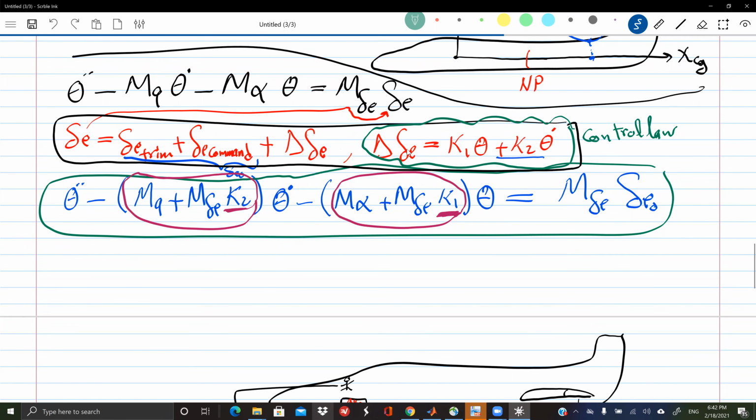If someone magically gives me, okay, at this instant give 2 degrees elevator, next instant 2.5, next instant -3 degrees elevator, okay, I'm fine. Just give me how much elevator I should give at each instant, and I'm done. The power of this theory is that it gives you an equation where you just substitute at each instant and give the right amount of delta elevator, and it works universally. It works perfectly well continuously with flying. This magic equation is what we call the control law.